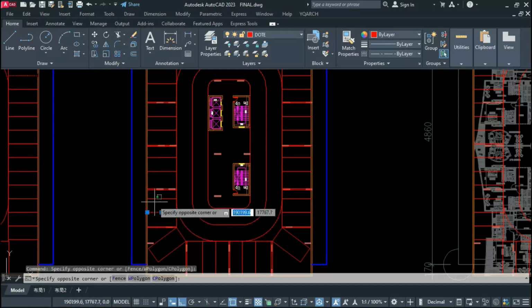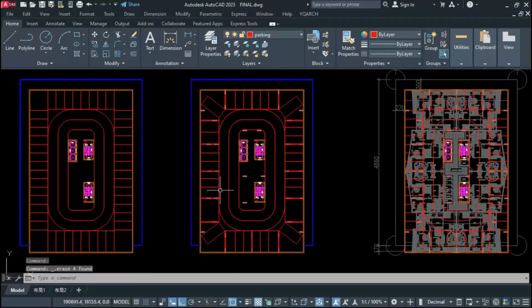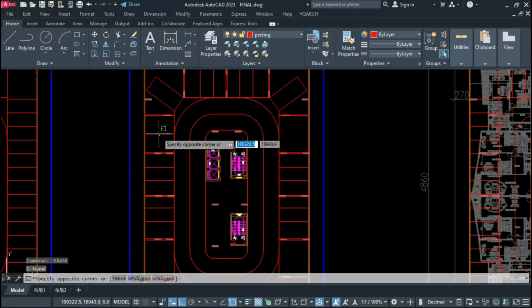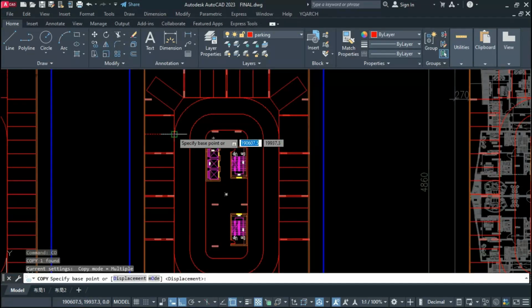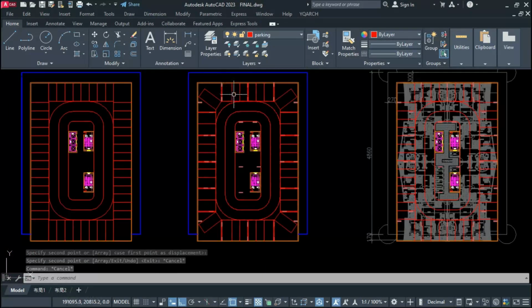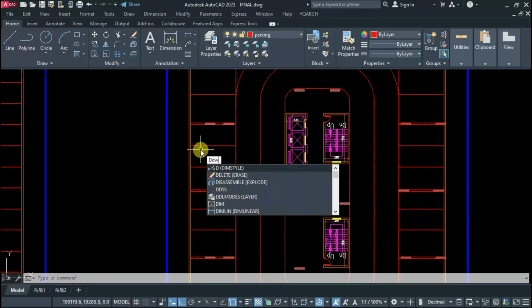This is okay. We are getting something like this. Our complete parking area as per column layout, as per typical planning. Now, whatever inside we are getting, that simply remove because we have made already center to center. Let this here. It must be equal and let this here also. This is okay. So number of car parking we are getting over here. As per typical plan, we must provide for each flat apartment: if we have more than 150 square meter, then we have to provide number of 2 parking for each flat. If we have less than 150 square meter, then we can provide 1 car parking.